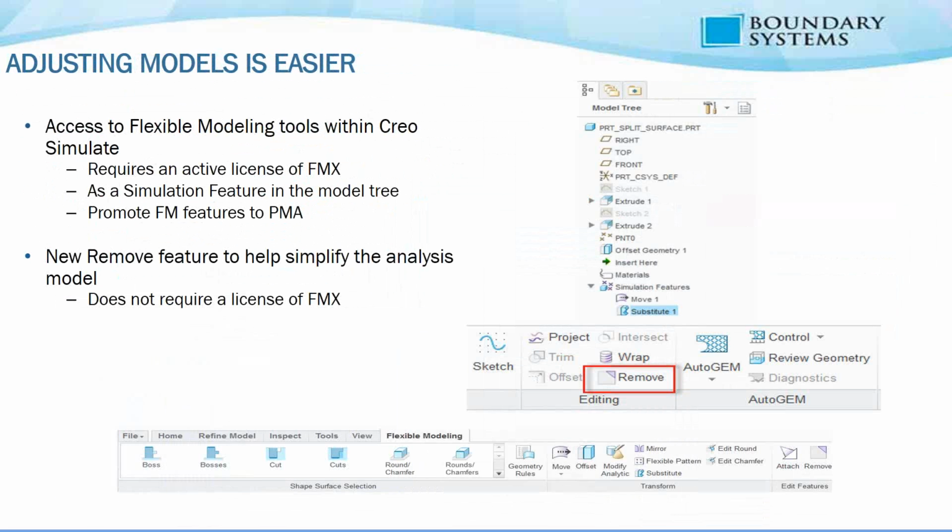You can manipulate your step files and things of that nature to further meet your design intent. Okay. So a flexible modeling license is required within your license to enable this to work, though.